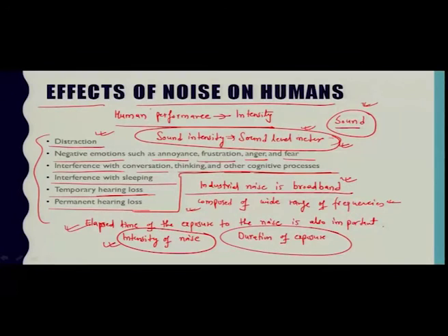The two most important scales are designated A and C by the American National Standards Institute, ANSI. The difference between A and C is that they electronically weight certain frequencies of the sound pressure signal differently. The A scale is weighted to approximate the hearing response of the human ear, and for this reason it is the most commonly used scale, and the one used by OSHA, the Occupational Safety and Health Administration.